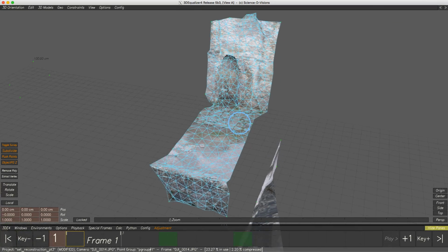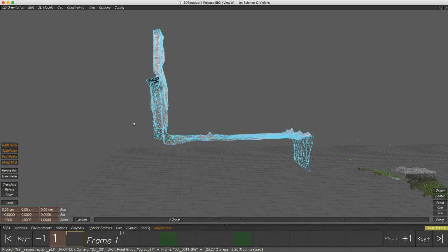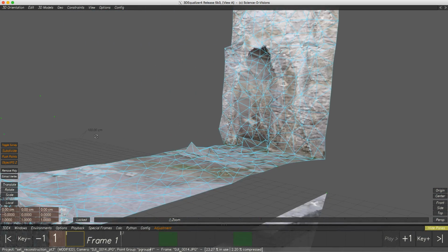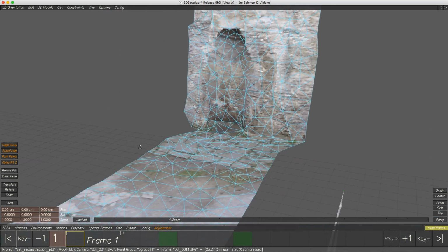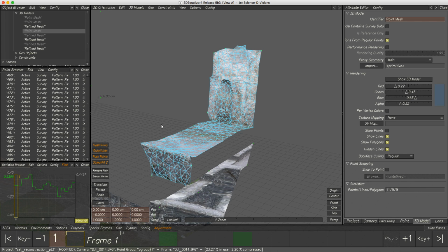Nice. This looks much better than before. The interpolation at the edge is gone and even details like the setback in the wall could be refined. Even better, this refinement didn't last longer than the other 2. The reduced amount of used cameras really helped having a performance destroyer like parameter quality set to 1. And again, we have a nice low poly model. Of course, there's room for improvement, but for this demo, the result is sufficient.